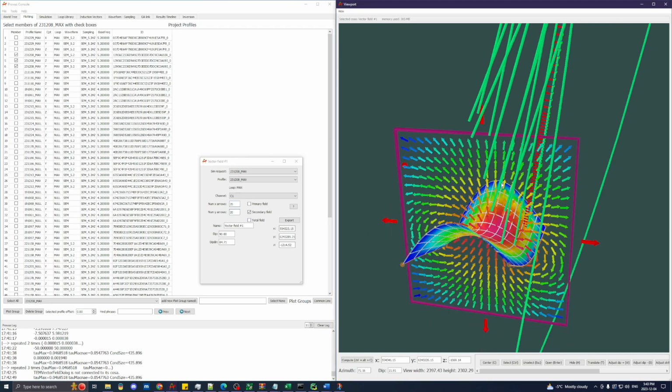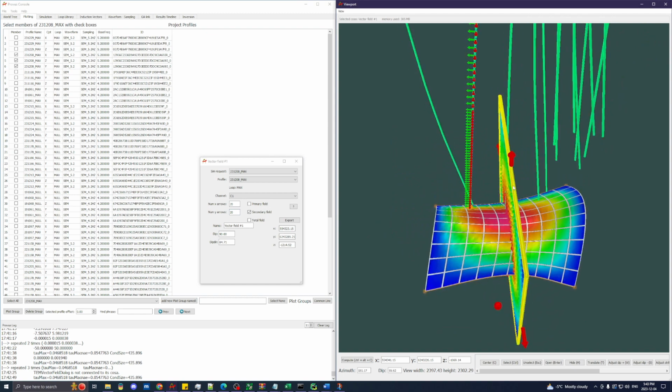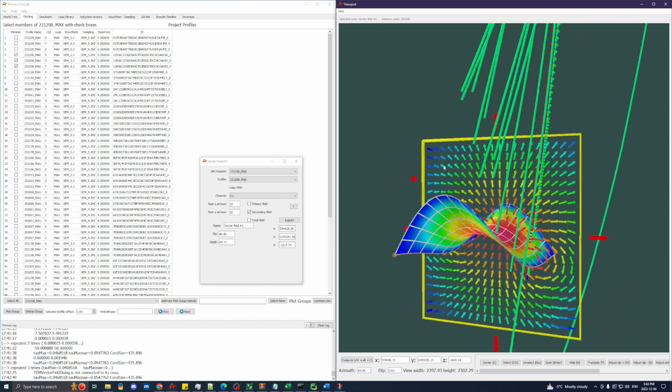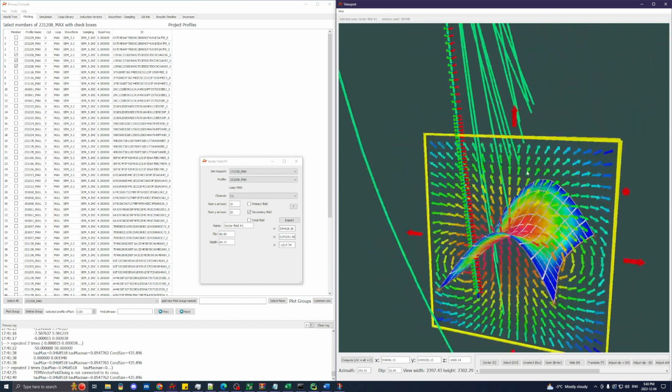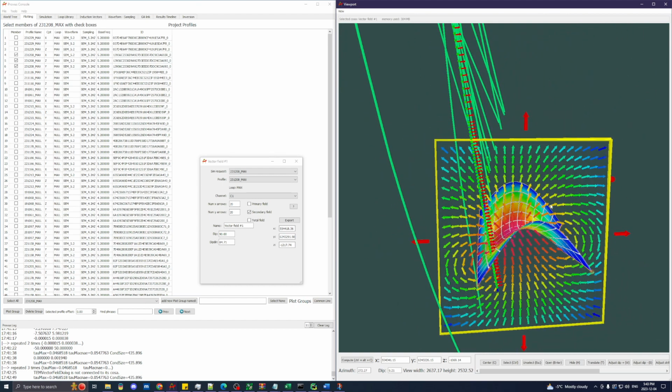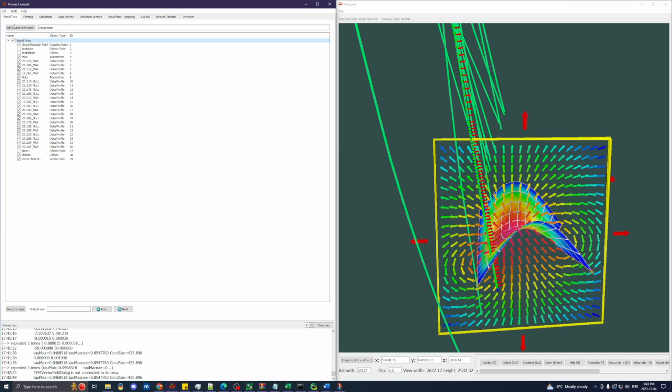As you drag your vector field to different positions in your viewport, it will automatically update. So this is a really useful tool, both for just gaining a sense of what's going on with your fields relative to your conductor. It can also be useful for things like survey planning, for designing loops that are null coupled or max coupled to some assumed target. That will show up in your world tree as vector field number 1, and you can toggle it anytime you don't want to see it.